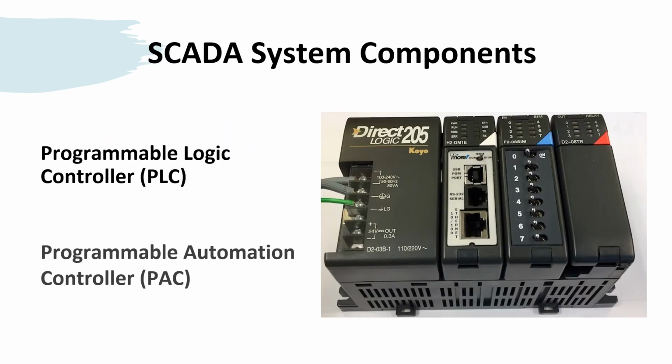A PLC is a self-contained computing device that is geared mostly for industrial control. It is programmed to realize the various functions required by industrial processes, such as robot controls, equipment operations, and status diagnostics. The PLC instruction set may include logic, timing, counting, communication, math, and input-output I/O control. An Ethernet-enabled PLC is shown in the diagram below.